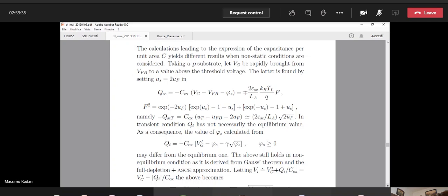And this action is almost immediate, almost in zero time, because the time constants of this phenomenon are very short. So you create almost immediately at the application of the positive pulse a region that is fully depleted because I pushed away the holes and there are very few electrons.